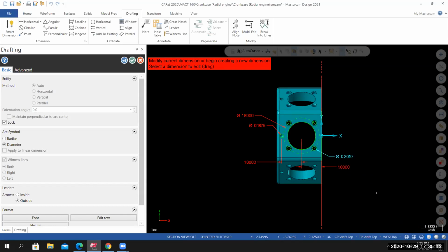I have a question. Yes, sir. Mine's giving me a warning saying the construction plane is perpendicular to the graphics view. Did you change the C-plane to the top, or are you still in a right side C-plane? I got it. All good? Yeah, so if the construction plane's weird or not correct, it's going to give you that error.